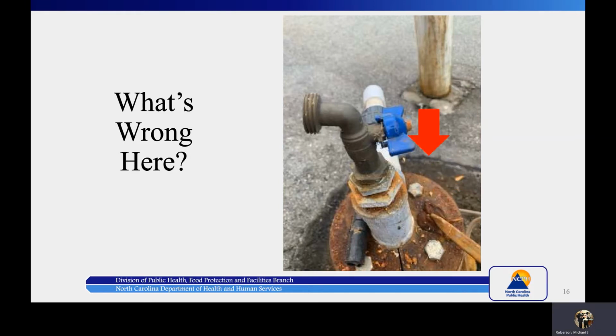You might also say that the asphalt around the well casing has some seams, where maybe asphalt was poured up onto the edge of another pouring of asphalt. We may have concrete underneath there. We've got a metal post over here. Any one of these things out in the middle of a parking lot like this can divert water down towards our well and cause water to pond up around it.